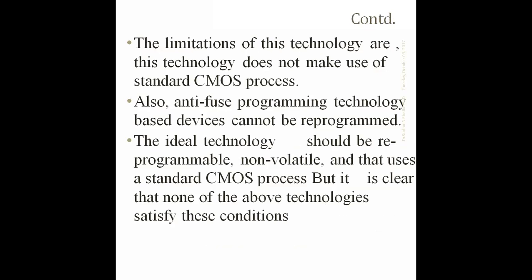Antifuse programming technology based devices cannot be reprogrammed. Once we have programmed, it is permanent and cannot be reprogrammed. The ideal technology should be reprogrammable, non-volatile, and use the standard CMOS technology, but it is clear that none of the above technologies satisfy this condition. The basic conditions are that we require non-volatility and a standard CMOS process.